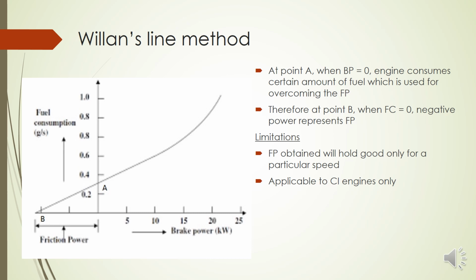Second, the method is applicable only to CI engine, because in an SI engine we cannot make fuel consumption zero, since the air-fuel mixture will already be entering. So that concept will not hold for SI engine. So this is applicable only to diesel engine or CI engine.